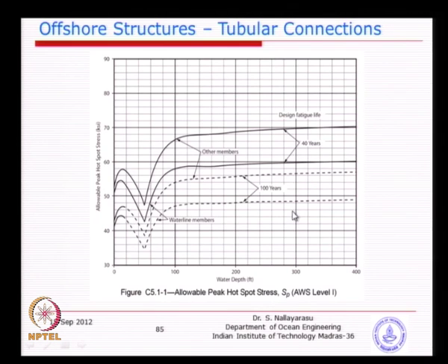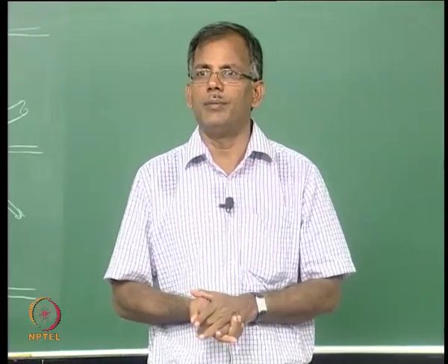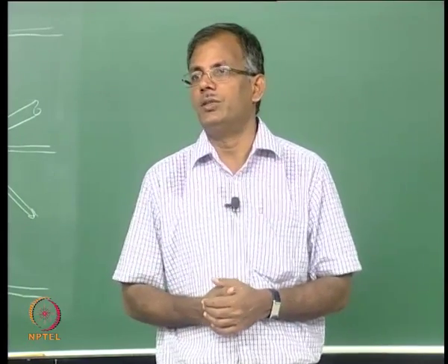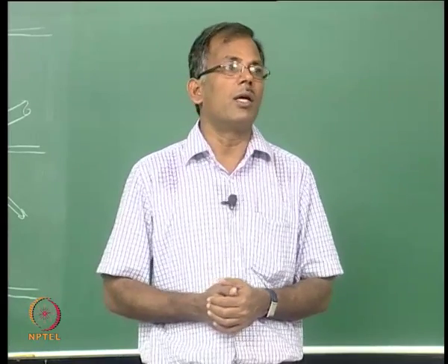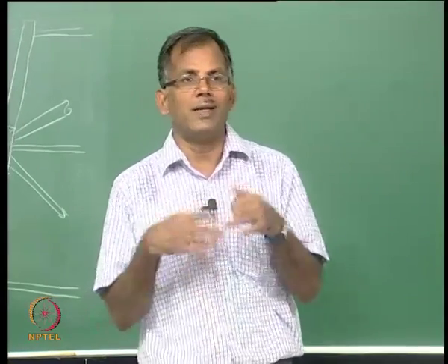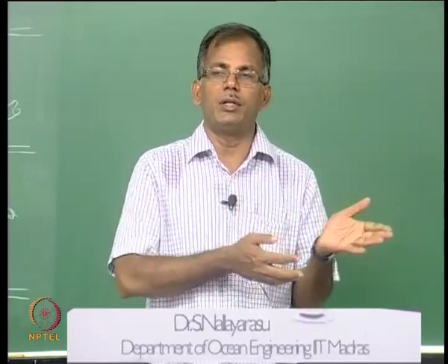This is again based on Gulf of Mexico studies. All these recommendations given in API, remember all of them are only, I would say, 100% applicable to Gulf of Mexico. If you read the API preface, they will say you should apply your local conditions before applying API requirements anywhere else, because the codes are developed only for their region of interest. Whereas when you apply to Indian waters or elsewhere, you need to make sure that the parameters you are looking at are similar, or at least you are aware of the things that they have done.